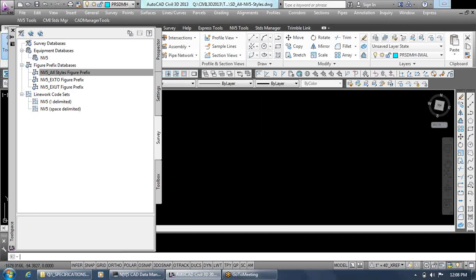Do not create annotative hatches. That's a known problem with undo functionality. There are also forums that talk about associative hatches causing issues with the undo. I know sometimes you need to use associative hatches, but just be aware that when you use them, you may start to experience issues with the undo.